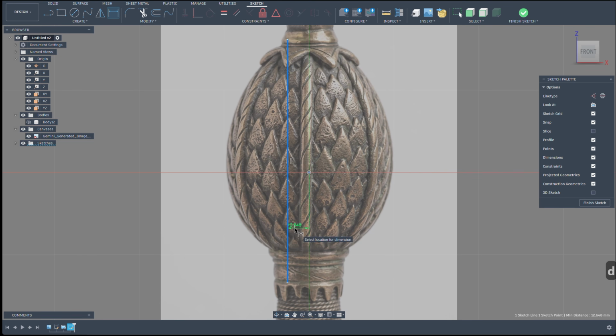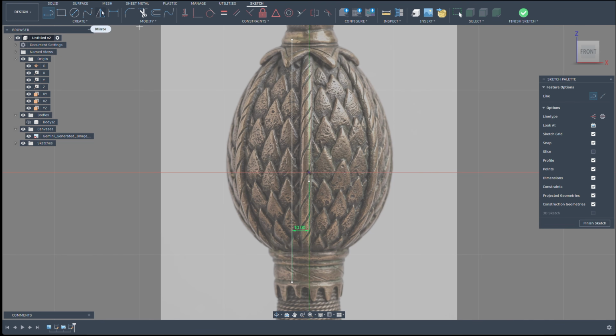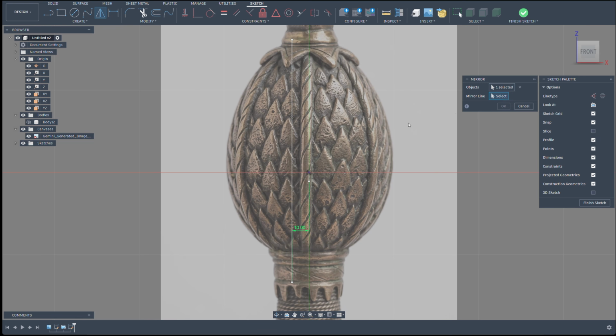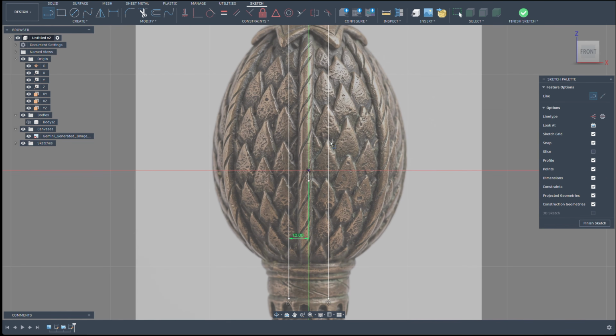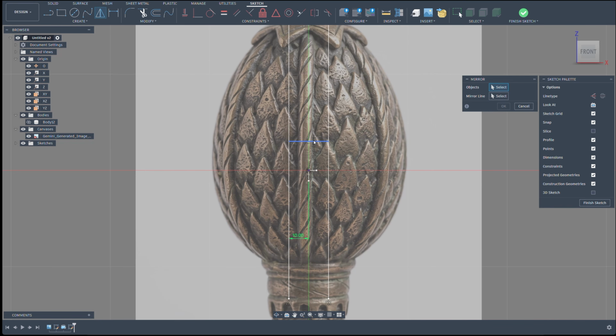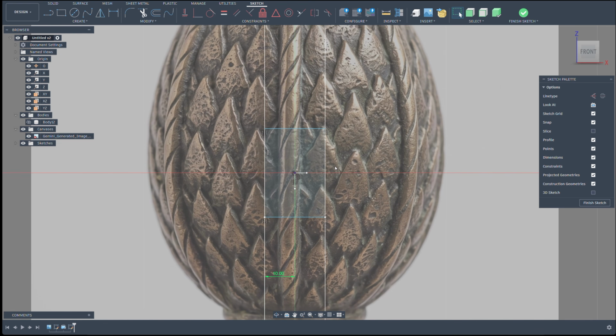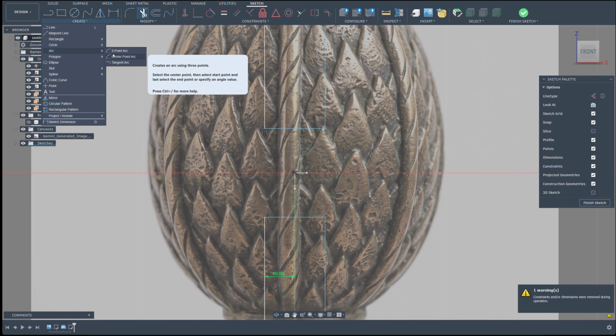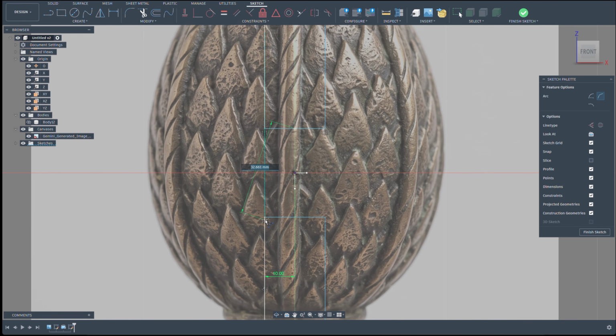I am creating the scale profile at the level of the base circle center. Let us transfer the scale height from this fragment. For convenience, let us mirror the boundary downwards, since we do not know where its true base is. Using the arc tool, we will create the sides of the scale. Done.